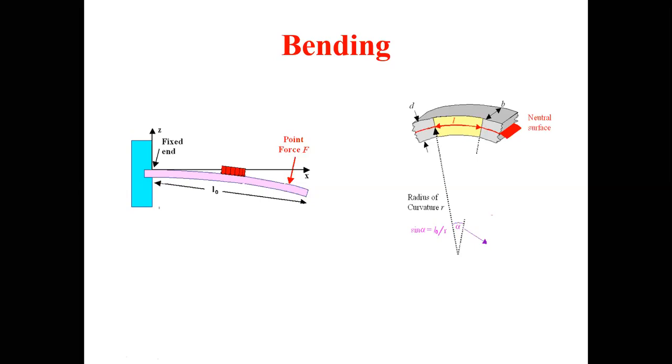Okay. Now, if you can see that if this is the section of the beam, upper surface has undergone extension, the lower surfaces or lower layers, you can say, they have undergone compression, and in between this there is a layer which does not undergo any sort of extension as well as compression. This surface is known as neutral surface.